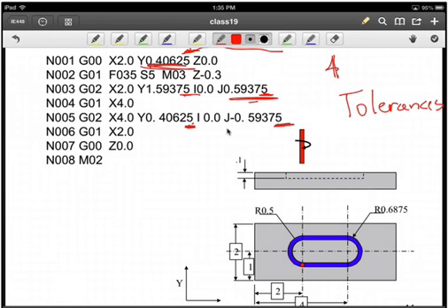We have to add additional radius to make sure we're in the right location. Here we're going to subtract the additional radius to make sure the center is in the right location. And it's really only impacting our y values. So now we have the corrected program, and if we fix these digit problems, then it should run.